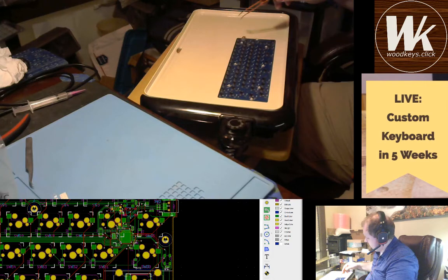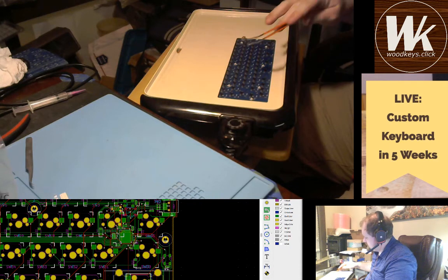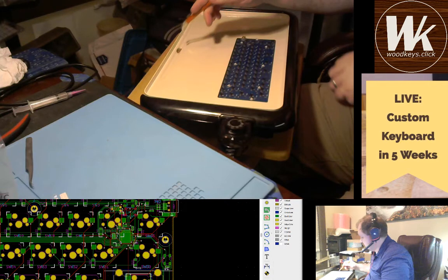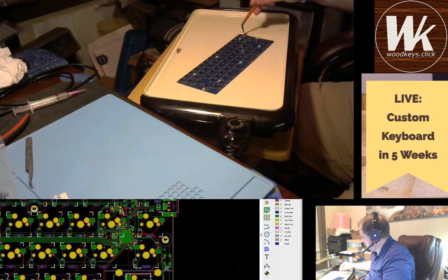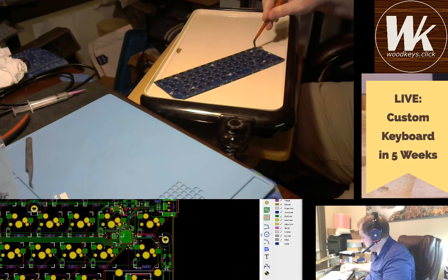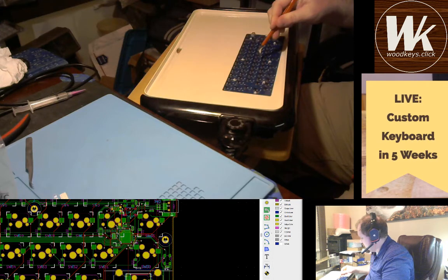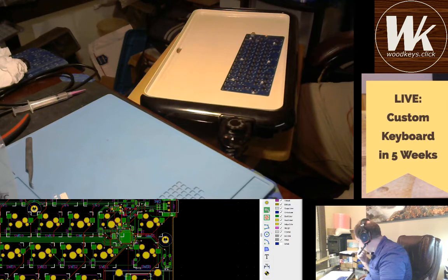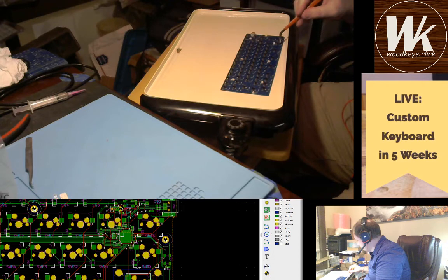One problem with this whole setup is that this skillet is curved toward the middle to allow the grease to flow over there, and so I do have to move these around and kind of make sure that they're reflowing evenly. I'll even kind of press them down in the middle because that'll pop back out later. Trying to make sure that all the components are getting properly heated.